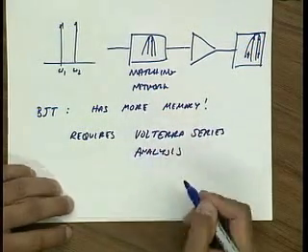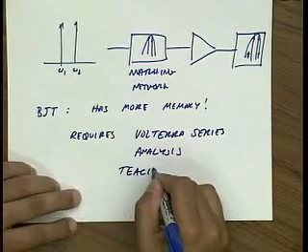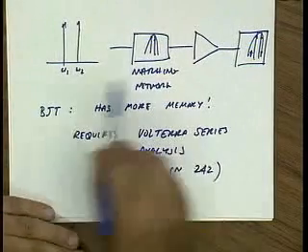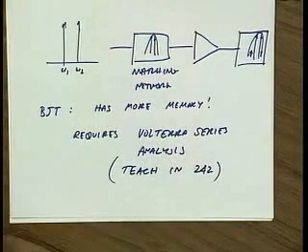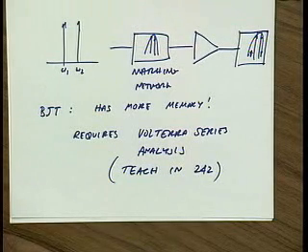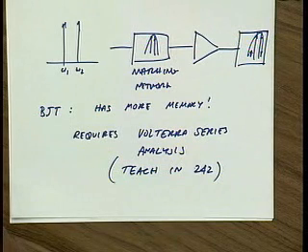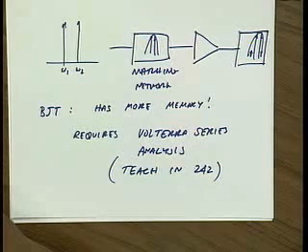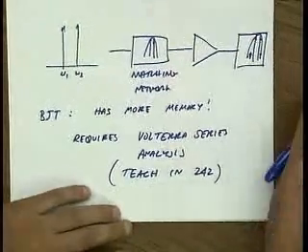This is something that we teach in 242. But it lets you take into account the memory effects in a bipolar. What are some of the memory effects in a bipolar? Exactly. It's the tau f. It's the diffusion capacitance. You have junction caps just like you do in a MOS, but then you have this diffusion capacitance, which in combination with the junction capacitances makes the device have memory. Okay? Any questions?